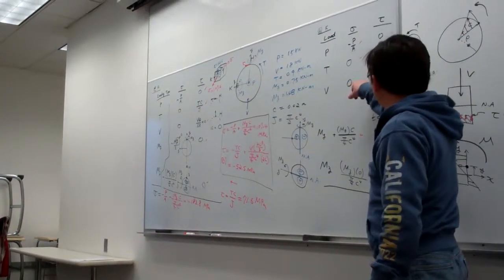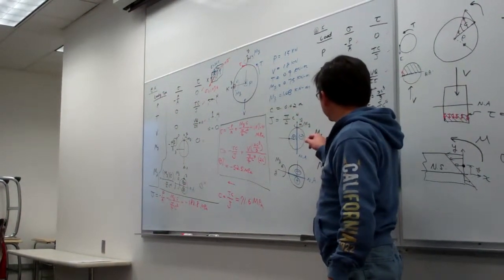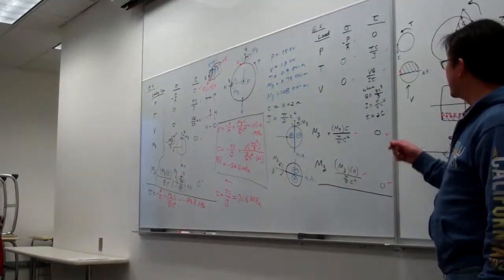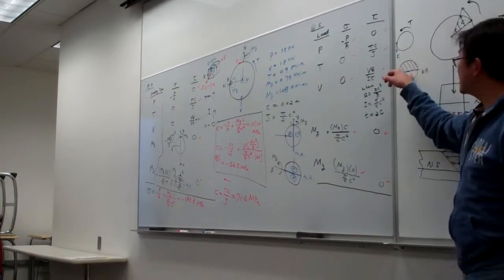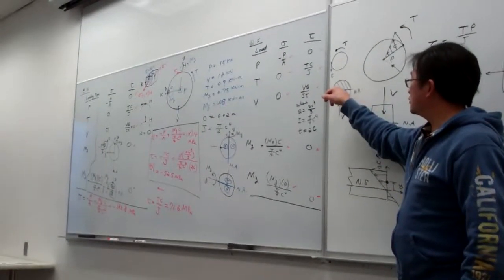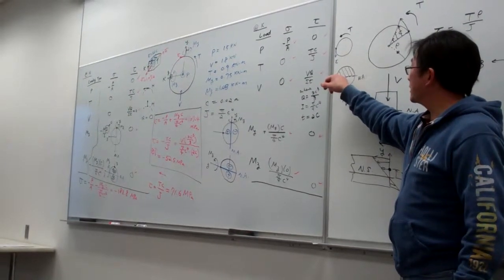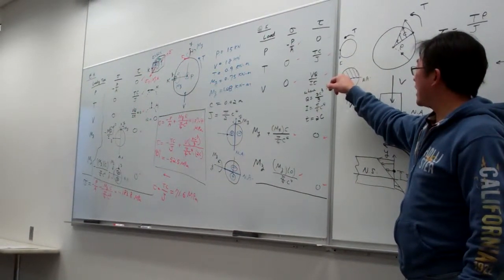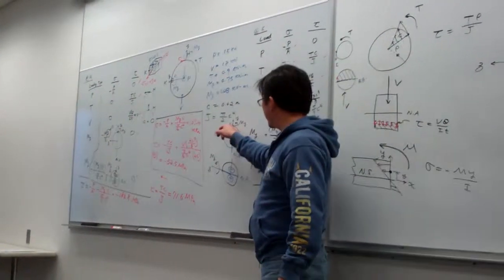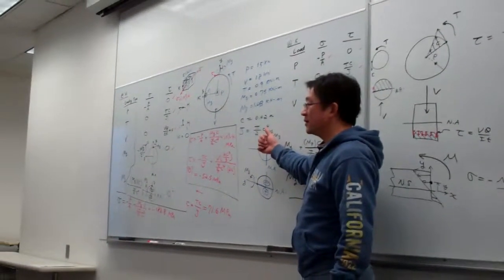In particular, you can see for this example, when we talk about this formula, we determine the neutral axis. Compared to when we talk about this equation, they have a different way of thinking. Again, let me emphasize, this is due to transverse loading. Determining the neutral axis is the way we pass through the centroid, and then the neutral axis is normal to the transverse loading. For pure bending, the neutral axis is the axis about which the bending is applied.